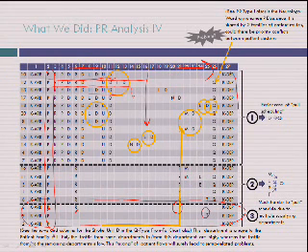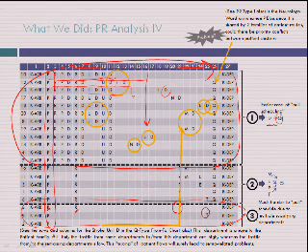If you take this family of parts and you aggregate all the routings into a from-to chart, you will find that Q, the department Q, which is neurology, only gets flow from department D, which is the stroke unit. So it's a lot easier to do pull scheduling and traffic management when you know that all your work into this department Q is going to come from department D.